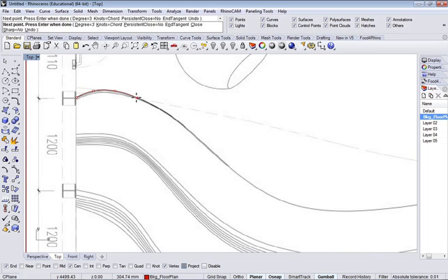And you can see where you need to add the next point to get the curve correct. Because if I go too far, you can see that it starts to fall below the line a little bit. Oops, too far. And so when curves happen that are tighter, the radius starts to get tighter, you need to have the points closer together. And then as long runs, you can make them further apart.